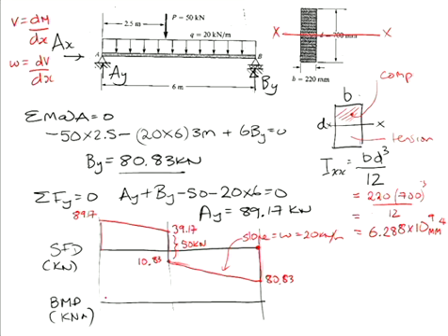So, bending moment diagram. Where do we know our moments are equal to 0? At the pin end and the roller end support. Value of 0 here, a value of 0 here. A positive shear force diagram, according to my relationship V is equal to dM/dx, means the slope of my bending moment is downwards. Why is it downwards? Positive is upwards. Remember, we draw positive down. Because we're using the sign convention, we draw it on the tension side of the beam.